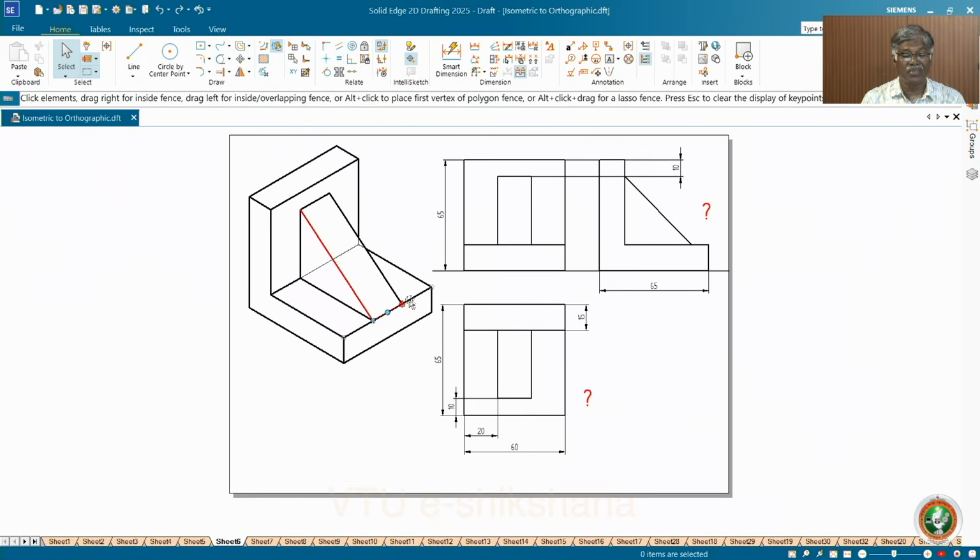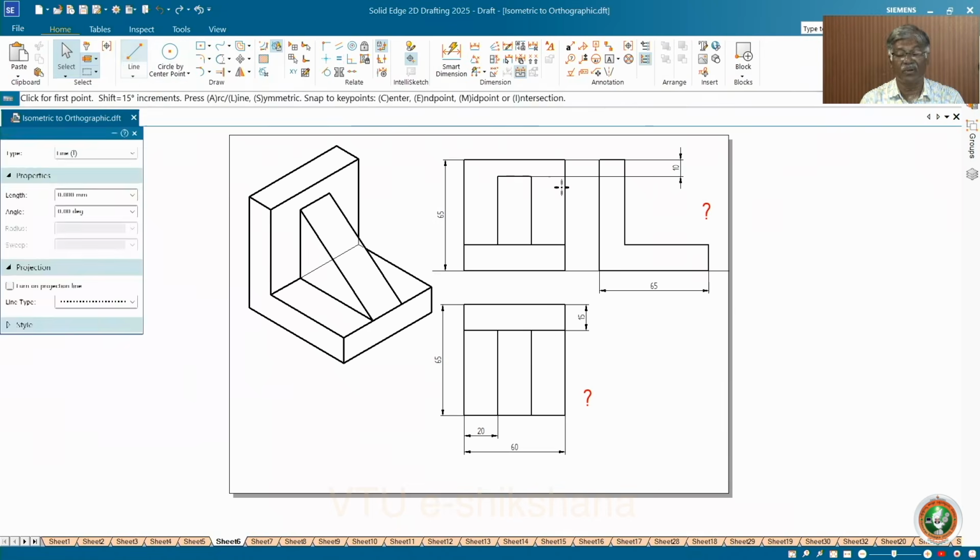Otherwise, the other way around, let me retain, that also is there. You retain here and gap here. Now look from top. Any changes you have to make? Definitely yes, because this particular point indicates the starting point is this and ending, there is no gap here in top view. Up to this it will extend. At the same time here, it is same. No changes because gap is there. Here I have to draw a line.